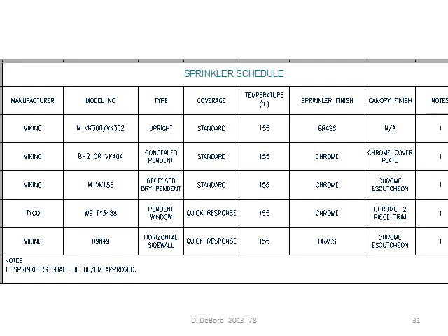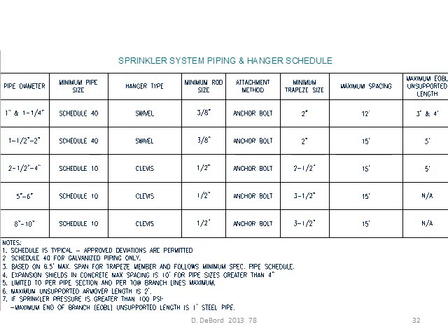You also should have something like this. This is a sprinkler schedule. So this has the manufacturers of the sprinklers and what type they are, model number, the coverage, where they are, and what the finish is. Remember, finishes always have to be approved by the architect. Everything for fire protection has to be UL FM approved unless there's some other indication for some reason.